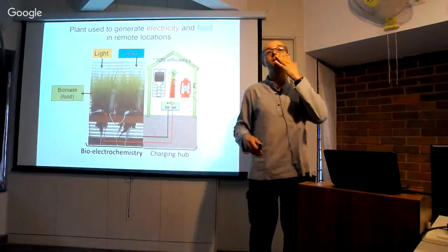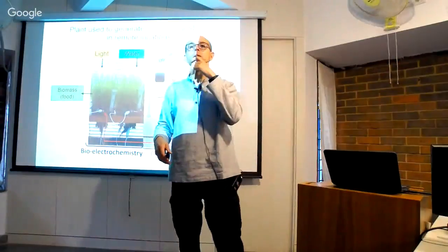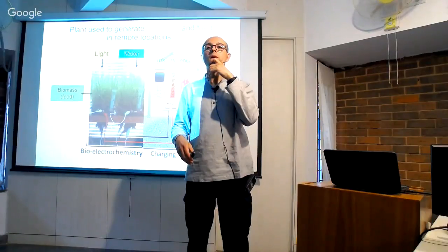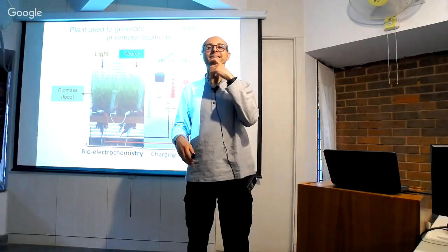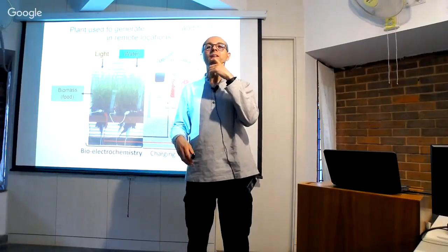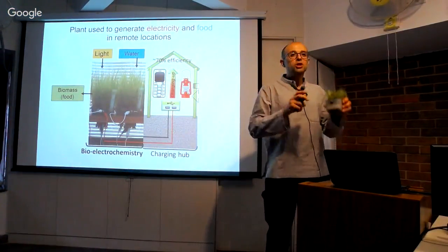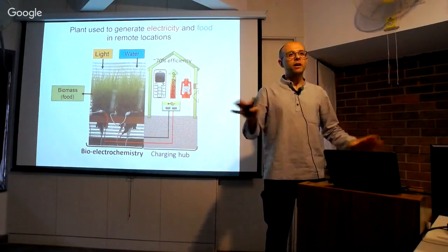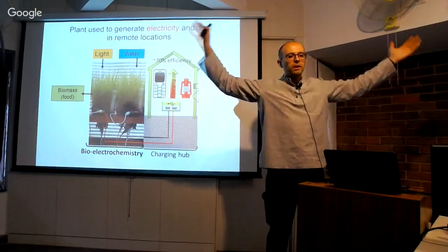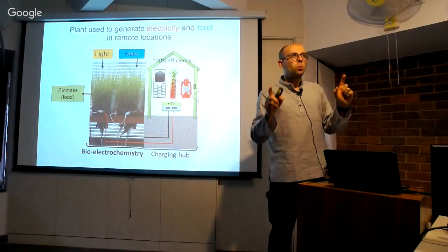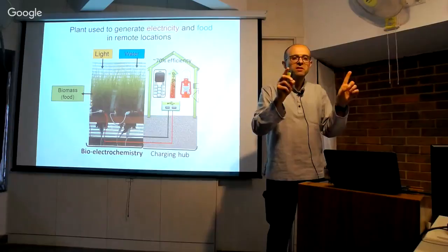Sorry. Is there any size restriction? Means you're using multiple small things for scaling up or increasing. Means is there a chance? Means if you, for example, as Durba asked, if you do it at farm level and use only one anode and one cathode, whether the scale of the unit matters for collecting the charges. So each unit, regardless of the size, can be tiny or can be huge. In terms of potential, it could generate no more than 1.1 volts. That is the theoretical limit.